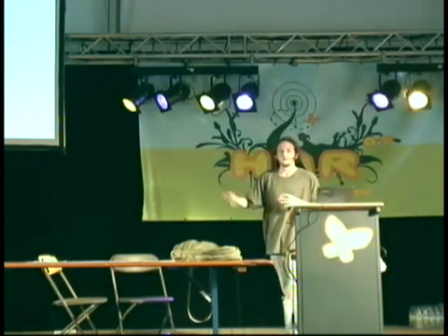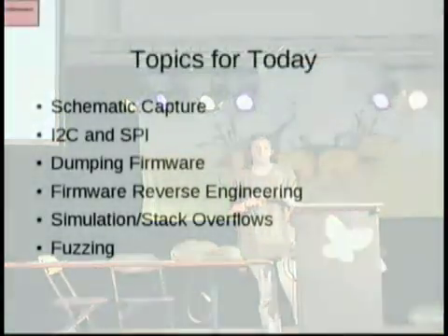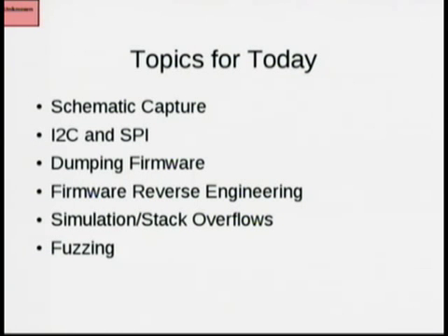So I'll discuss schematic capture. Given a captured device, you want to be able to figure out which wires contain which signals. And you want to be able to do this as quickly as possible. And thanks to the hardware-accelerated I/O ports of the chips used, you can be guaranteed that the particular functions will run over particular pins of each chip. We'll also discuss the protocols that are used to send data from one chip on a board to another, and how you can wiretap that line of communication, that internal serial bus, in the same way that you might wiretap a network using a packet capture device.